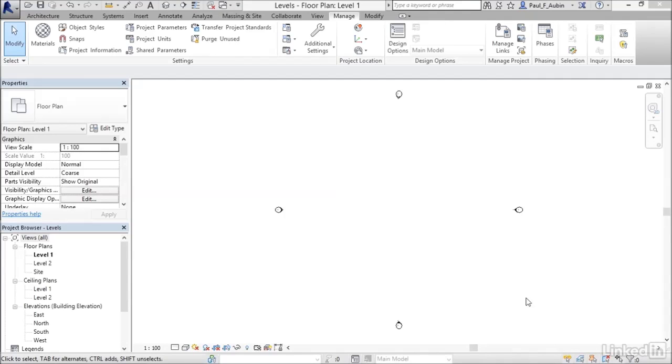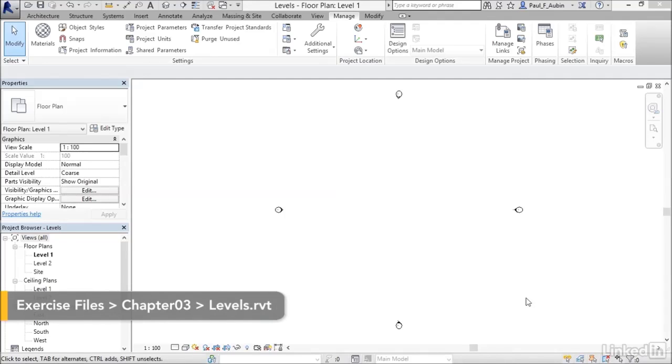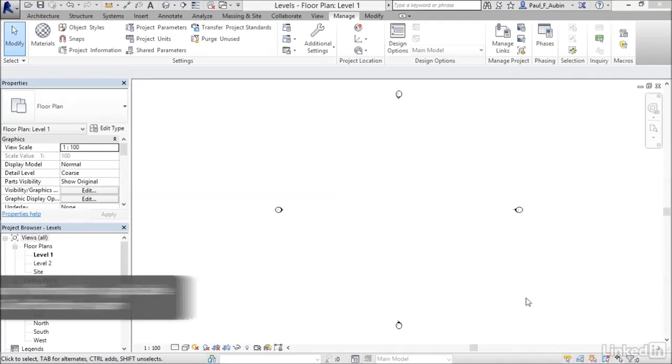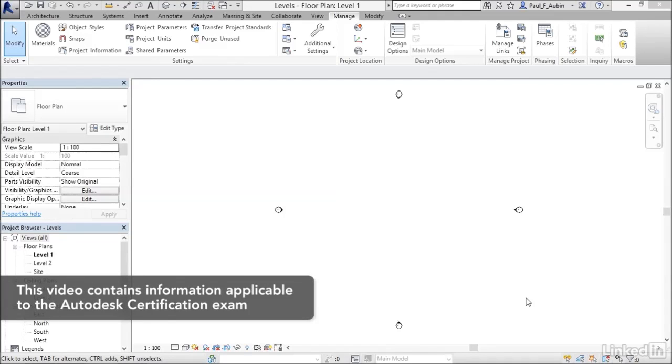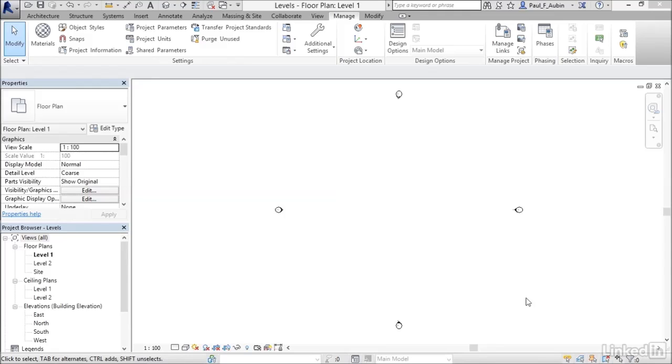Levels are one of the primary organizational and structural constructs in your Revit projects. They help determine where all the important heights are in your building. They can be in the positive or the negative direction, and they determine the important values in that Z direction. So it's very common to have a level at each story of the building. I always tell people if there's a button on your elevator, you ought to have a level there.